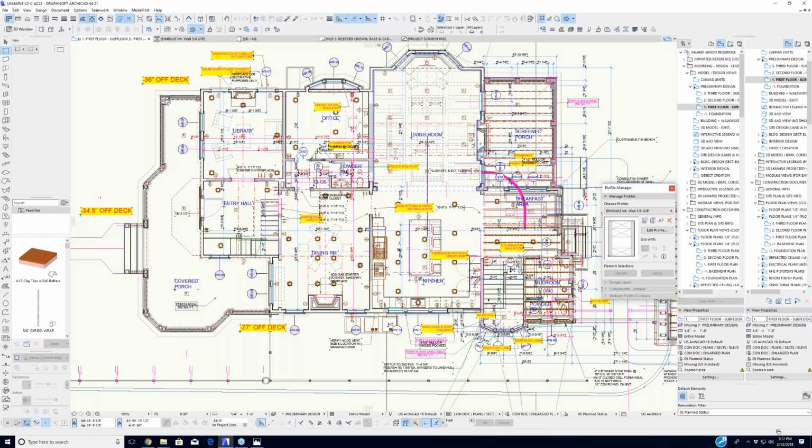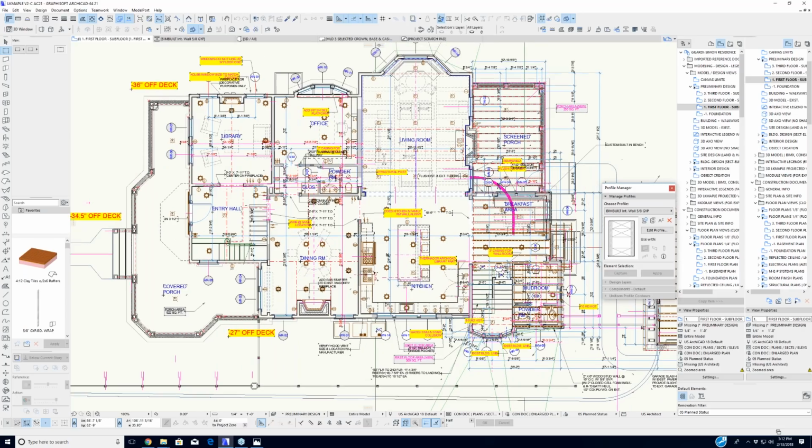The floors were 3 inches out of level. They might have put vinyl over it. There's what's called scab work. They would do a lot of scab work to get things level, but not fix what was actually causing the leak. Either way, I would measure this, taking about 2 full business days on site. So if you figure 16 hours, maybe even more, document every single floor.